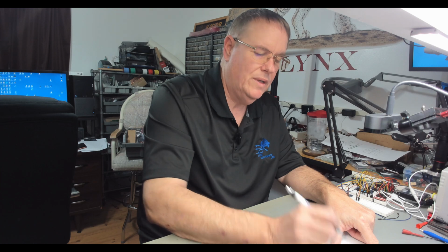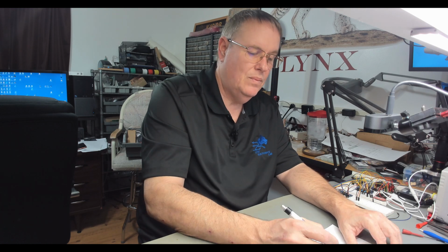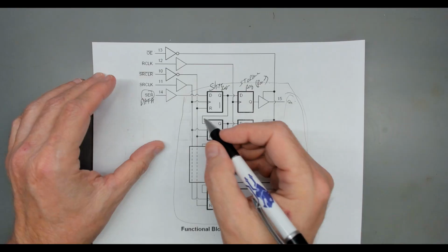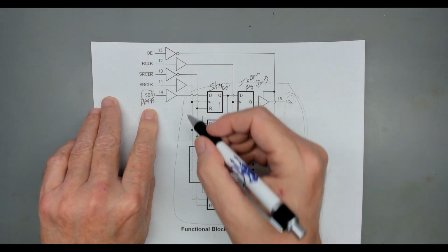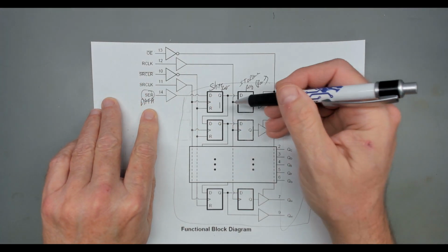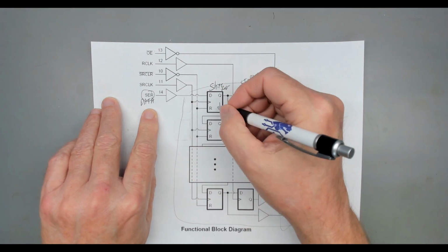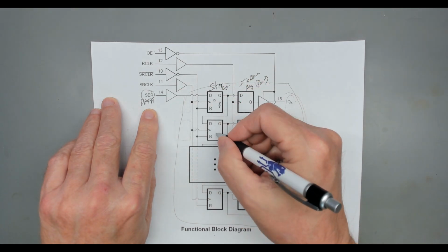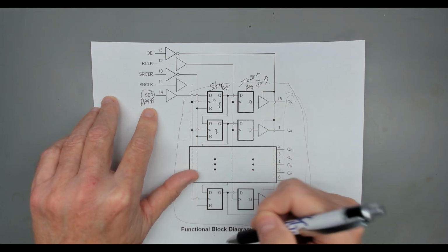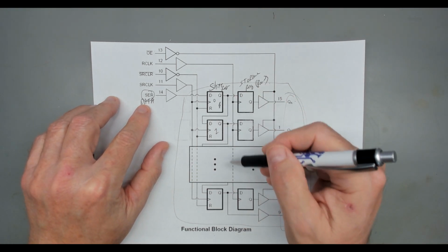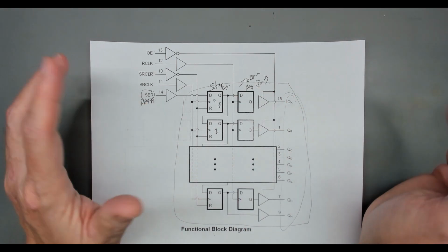Let's say it's a 1. Now, when you're ready to put additional data, say you set 0 here now on the data line, you cycle your shift register clock again, and 0 will move into this register and push this 1 to this one. That's why they call them shift registers. You keep shifting it down. And you continue to do this to load up all of your registers that you want loaded.